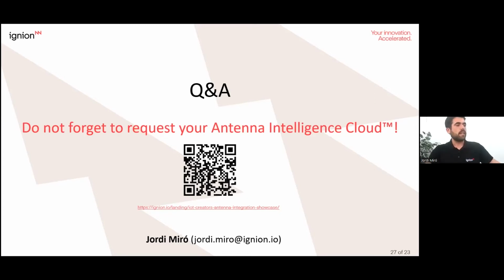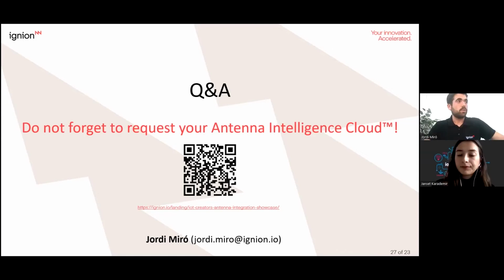The limitation of the virtual antenna is, I would say, the ground plane layer, and also the frequency bands. The frequency bands from 400 megahertz up to 10 gigahertz, we are okay, but lower or higher, it will be a limitation for us. So within this range, every wireless technology is working very well with our technology. But mainly the ground plane layer is the limitation. Very reduced PCB dimensions is a thing, but not only for virtual antenna, for every antenna technology.